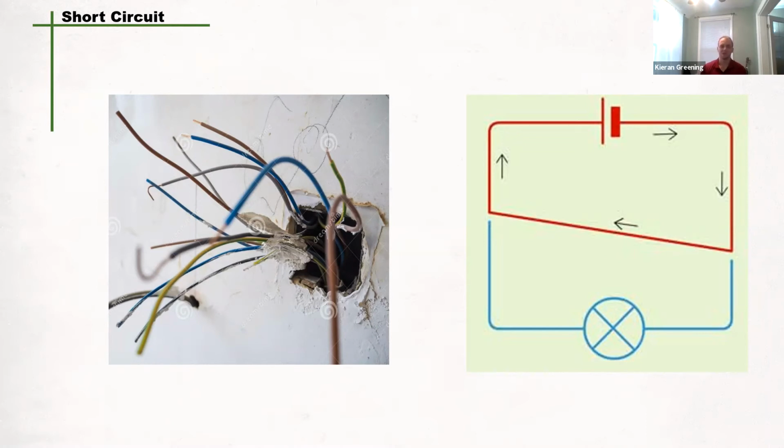So we'll just give an example of that. If a worker is carrying drywall studs through a construction site and there was exposed wire coming down from the roof, and an electrician or someone else tampered with it or forgot, any number of situations can happen on any construction site, and that's part of the hazard assessment process. So if that stud touches those 2 wires, it could potentially send a shock down that metal or any other piece of equipment that may conduct electricity.